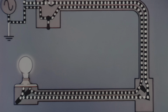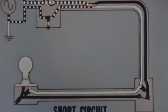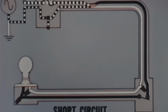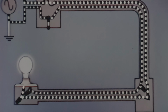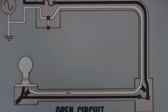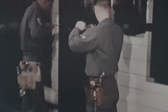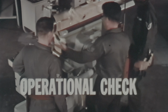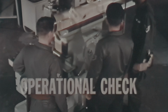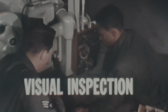Trouble in electric circuits can be classified into three general types: short circuits, grounded circuits, and open circuits. But regardless of the type of trouble, it can be found rapidly and safely by following sound troubleshooting procedures. Make an operational check of the circuit. Conduct a thorough visual inspection.